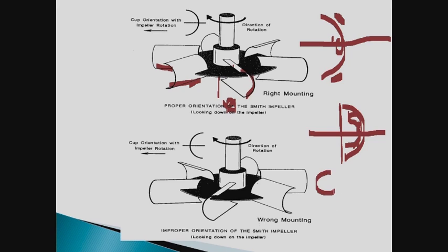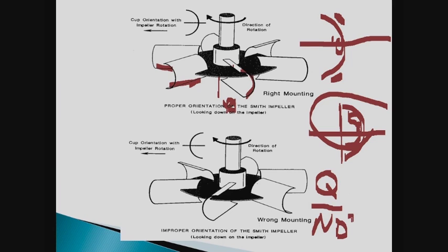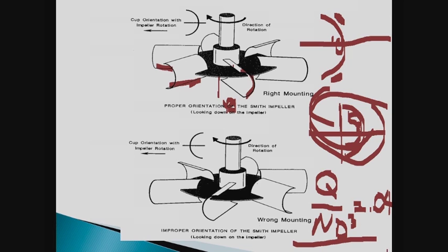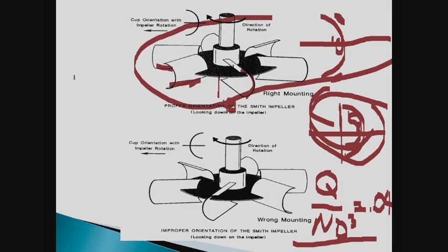Now, the flooded condition for that impeller, this one right here, is like this: the amount of gas coming in, and d cubed down here. This is called the aeration number. Okay, it's the gas coming in versus the pumping of the impeller. And what happens is this impeller becomes flooded at 0.04, right? 0.04. So a very, very small amount of gas, you essentially have very poor performance. This impeller here is supposed to go all the way up to 0.2. I'm not sure. Maybe more.